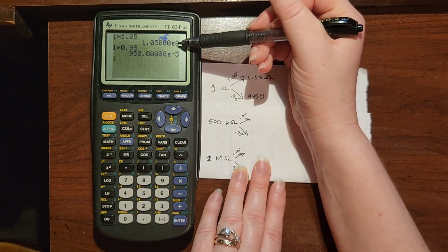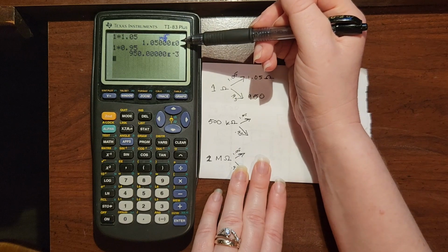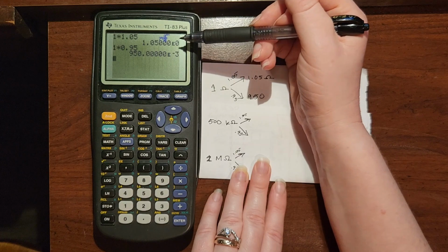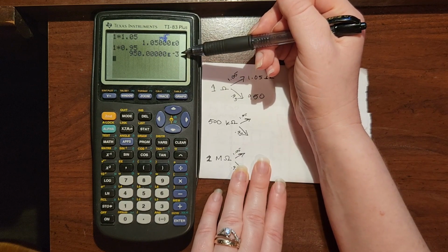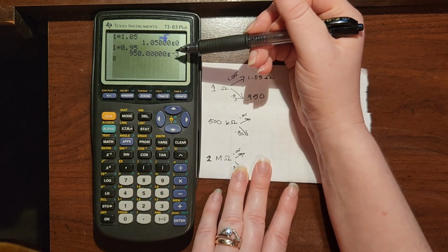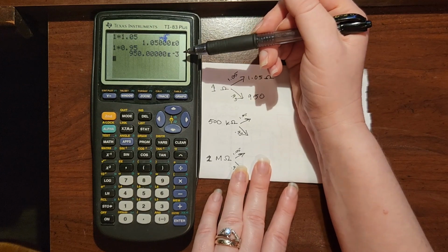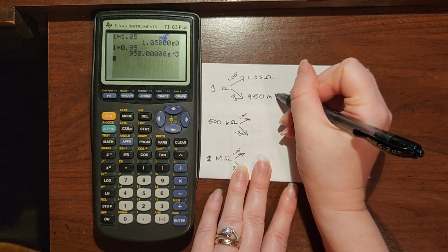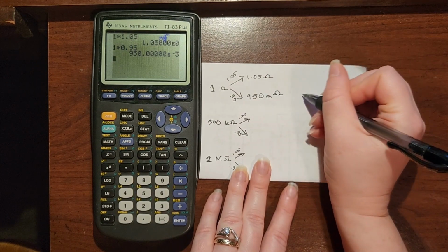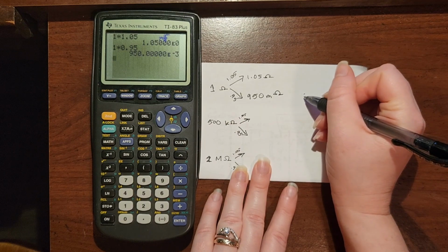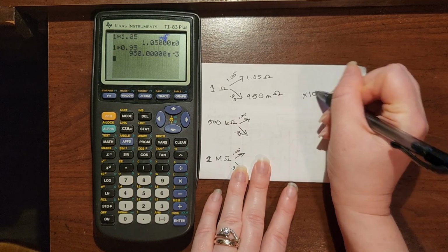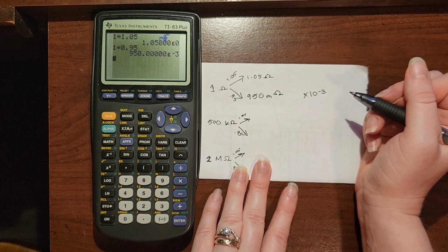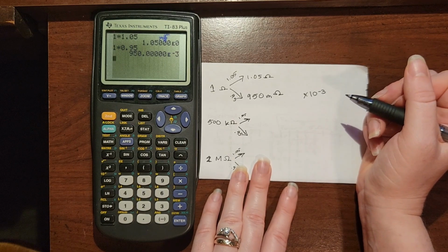But what you see at the end of the results here is an E and a 0. And this is saying that this is still just ohms. But when we multiplied 1 times 0.95, it's giving us E -3. And what that's saying is that this is now 950 milliohms. It's indicating that that is a result of times 10 to the -3. So that's going to be really important for your engineering notation.